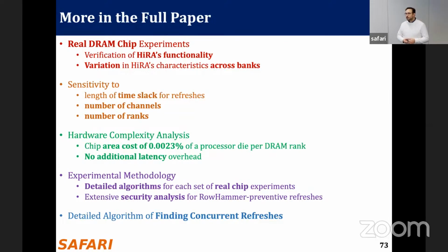One contribution of this paper is that after all these years, these operations are still not officially supported, but we can see this functionality happening in some DRAM chips today. So maybe those circuits partially already exist inside. This is more motivation for official support and for including them in the JEDEC standard so that we can leverage this parallelism. It could also be good to think about how we can combine this with other existing mitigation mechanisms, maybe to lower the cost.